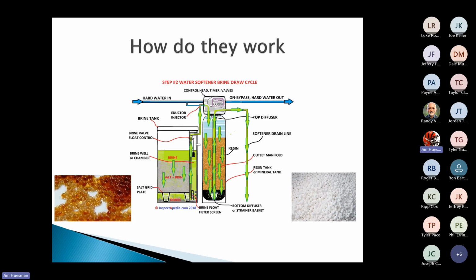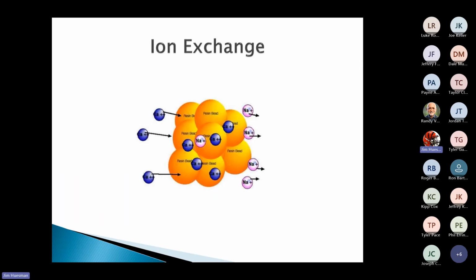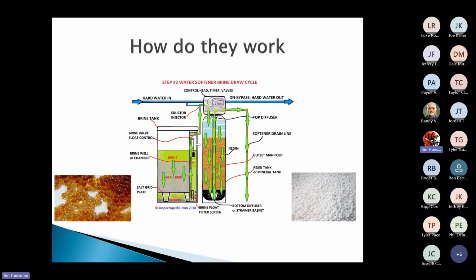Water comes up, it runs through all of our media, and what it's doing is it starts collecting, okay? But once you collect, eventually we're going to be full, correct? So if I'm grabbing a bunch of this stuff, it's hanging on. Eventually there's a time where, hey, I've got too much. I'm holding on to too much calcium, too much magnesium. I can't collect anymore. I'm pretty much done, okay? So what's going to happen is we have to go through a regen, all right? And we'll talk about that regen.